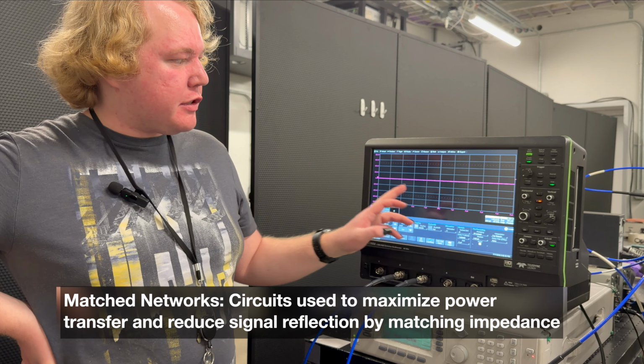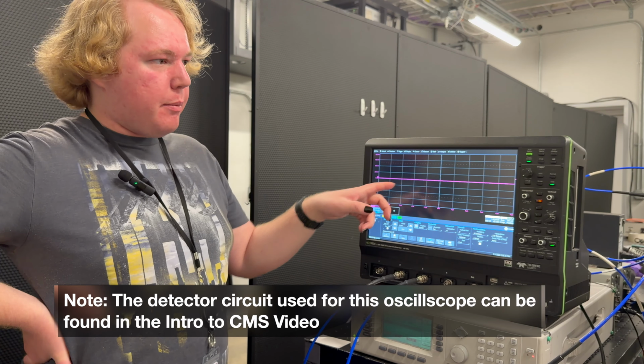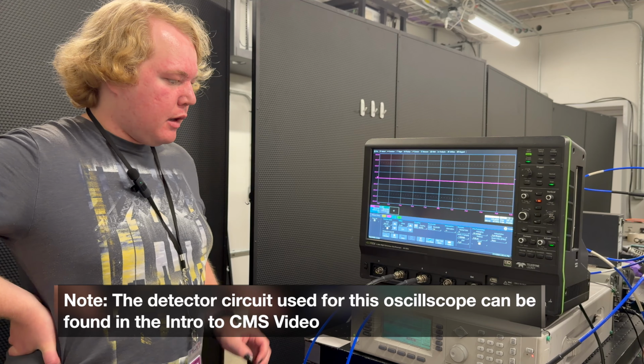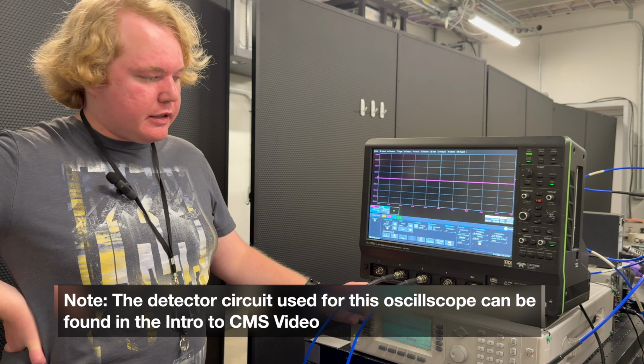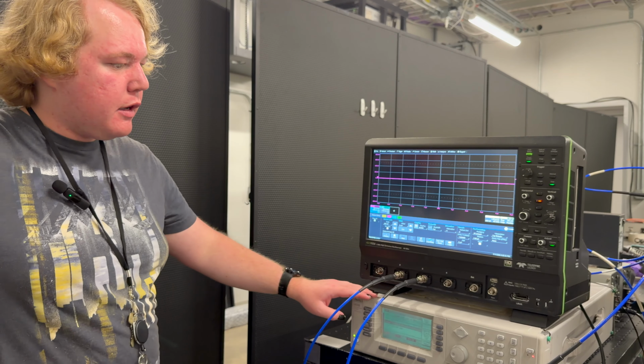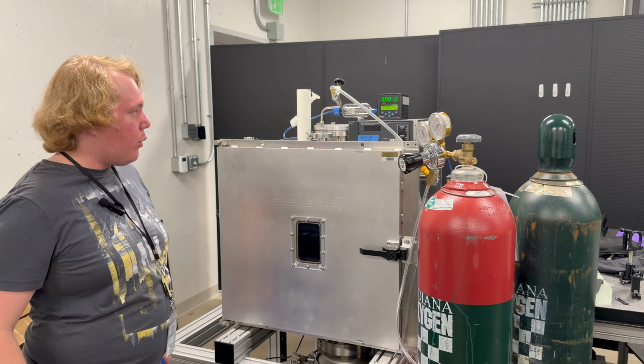As well, we average our signals, so as we're collecting them, it's averaging 50 sweeps together of the same pulse energy. And then we have the microwave generator here with the output set to 15 decibels at 11 gigahertz. And now we can go over a brief overview of how the procedure will work while we're operating it.